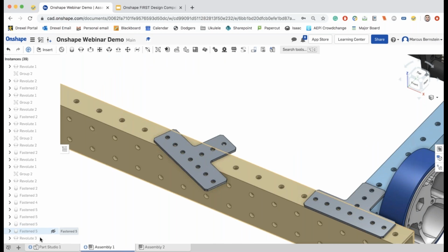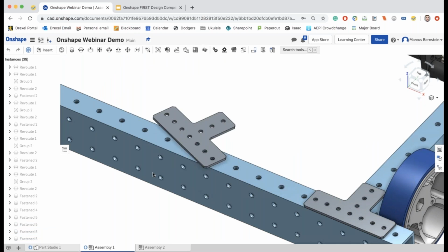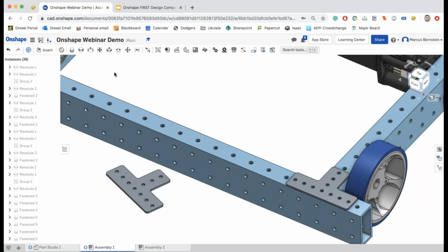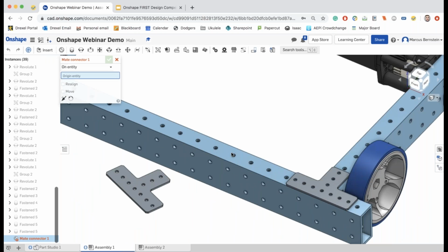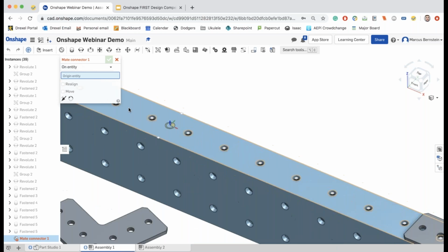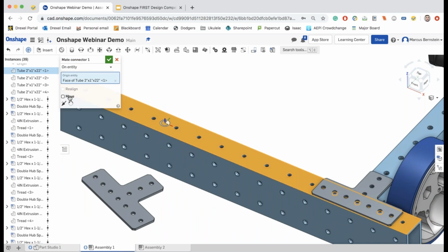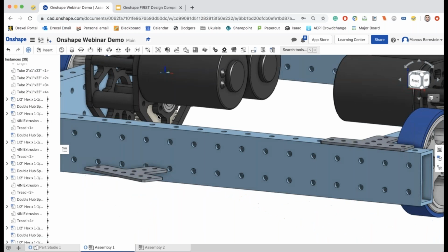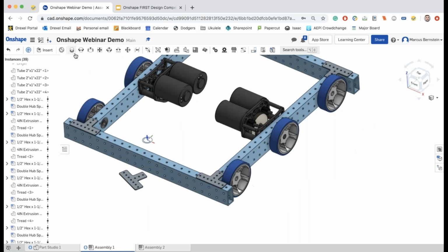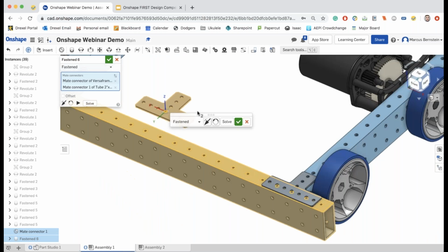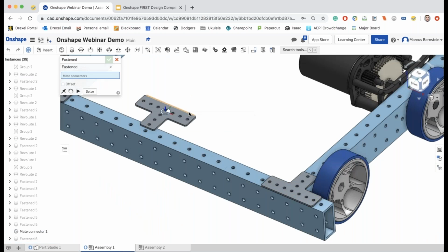The second thing, when you say a width mate, I assume you mean something similar to a planar mate with an offset. And for that, I would suggest the same two things. Build a mate connector based on a prior mate connector. Say we use this center point of that face. I can now move it. Say I want to move it 2 inches up or whatever. The mate connector now exists in space, and I can go ahead and do a fasten mate from this to that mate connector up in space.